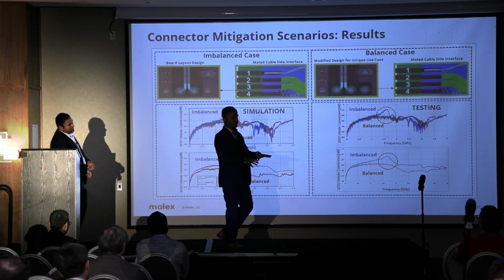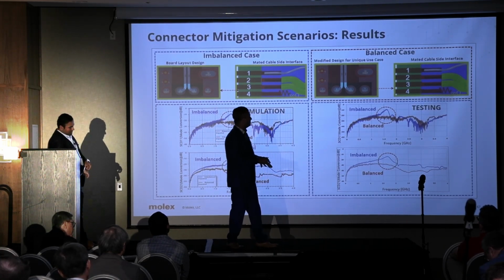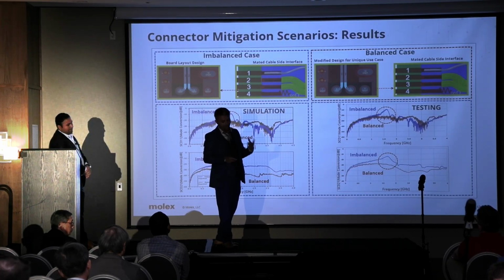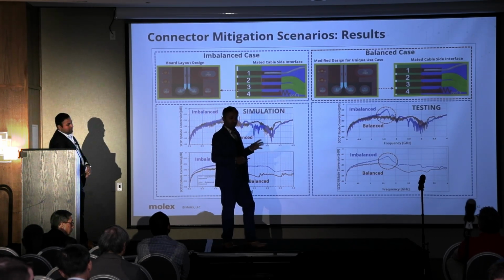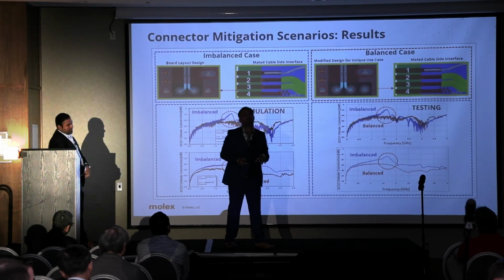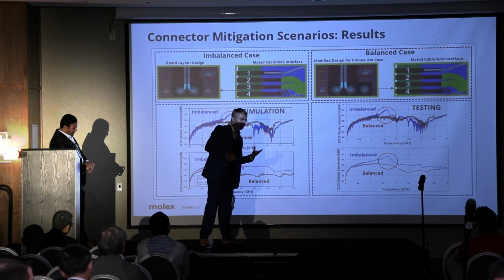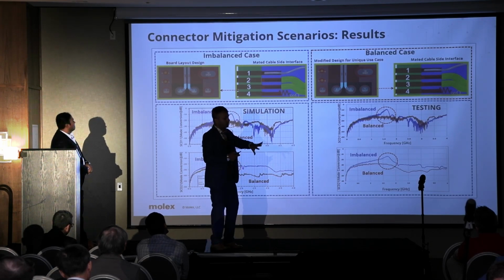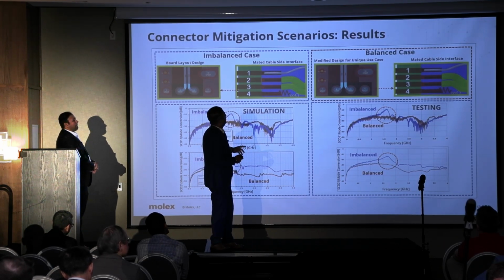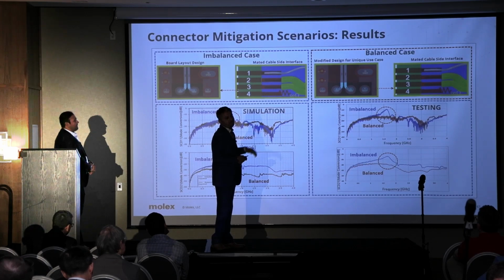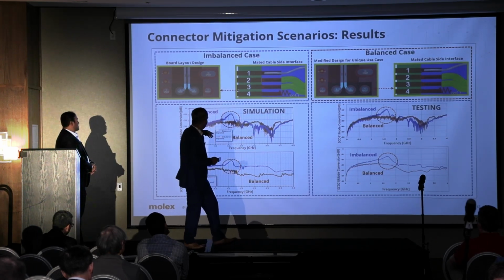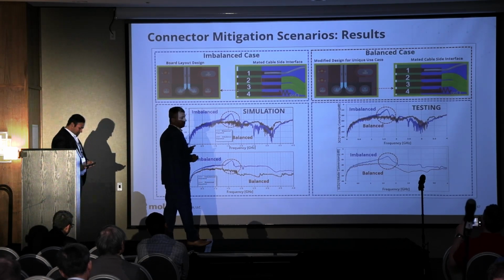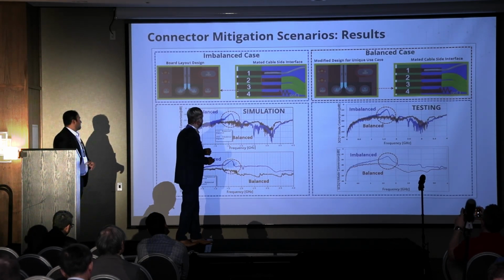But once I connect a connector that has only 3 pins connected on the cable side, where the pin is open, even though it's a design that is giving very good performance when I'm looking from a board level, in a system level, this will create a problem. And same thing, you can see the simulation and testing result. So the brown and the blue one, right? We have already shown this in the second slide also.